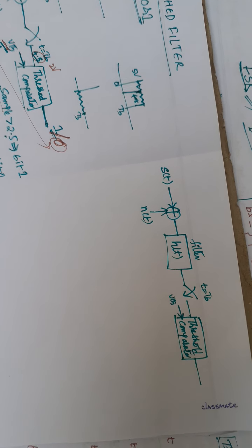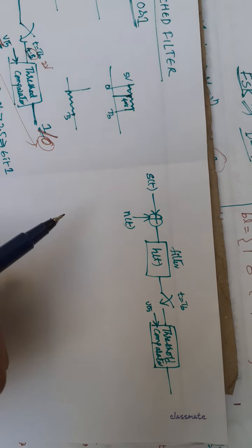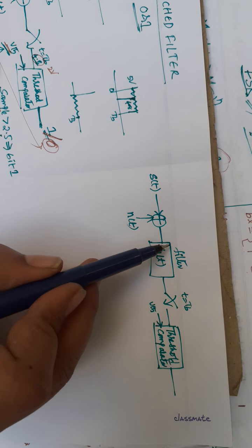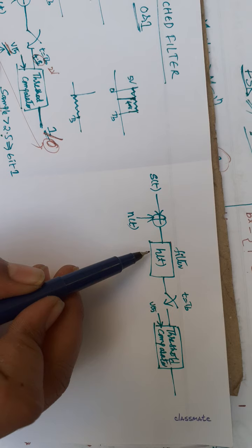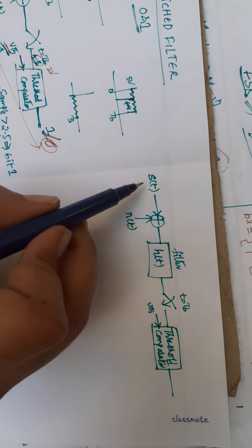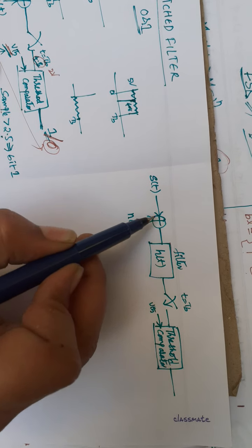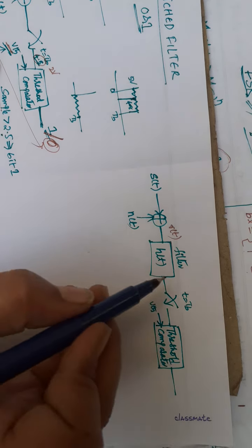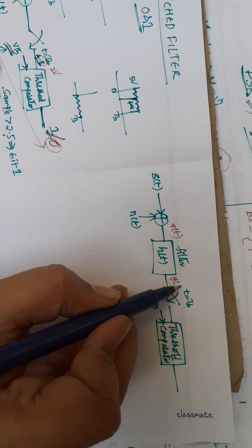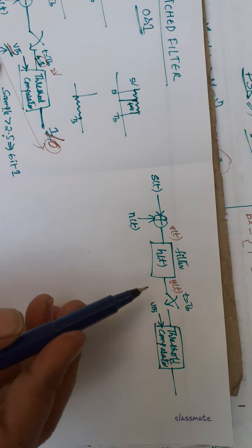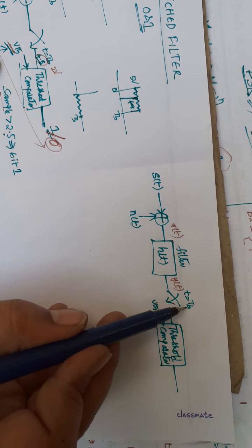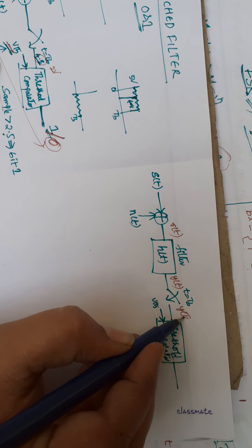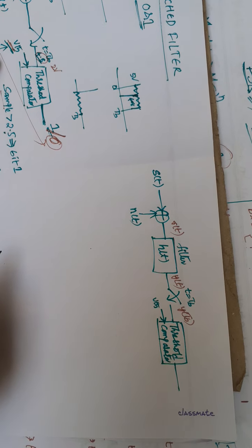Now see here, this is my new diagram. Just here I have inserted a filter to overcome bit error. Let us assume the output of my summer is R of t. The output of the filter I am representing here as Y of t. At t equal to T_B, the samples, the output here I call Y of T_B, right?